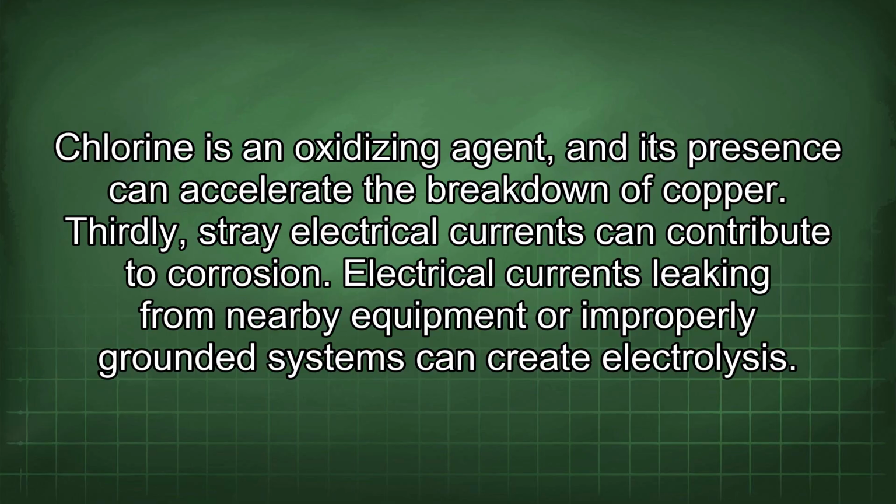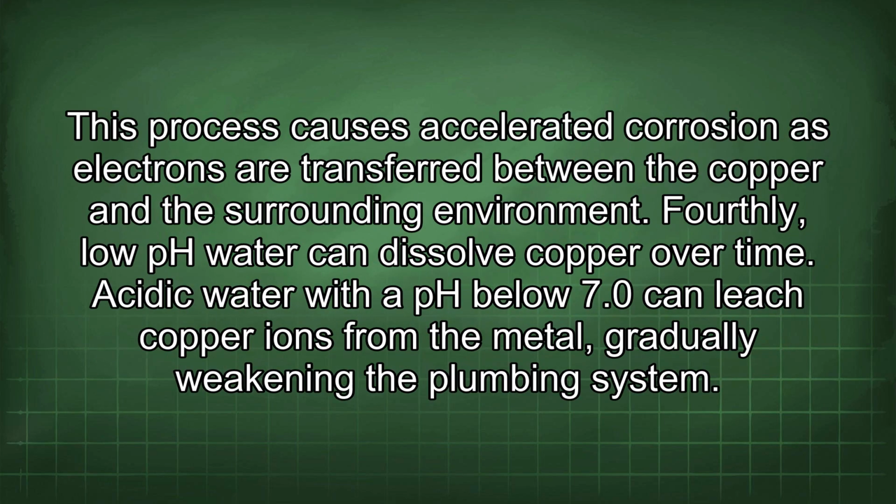Thirdly, stray electrical currents can contribute to corrosion. Electrical currents leaking from nearby equipment or improperly grounded systems can create electrolysis. This process causes accelerated corrosion as electrons are transferred between the copper and the surrounding environment.